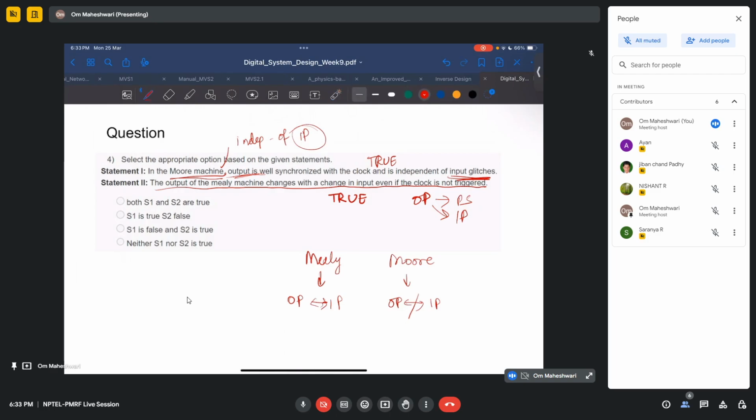Basically, in all these machines, you have some flip-flops and then some combinational circuits. After that, you get output. If input is being fed to this combinational circuit, this is input, this is output. The flip-flop's state will change only after it gets the clock pulse. But this output, even if the clock is not changing and the flip-flop remains at 1, will change from 0 to 1 depending just on the input, right? Is this clear?